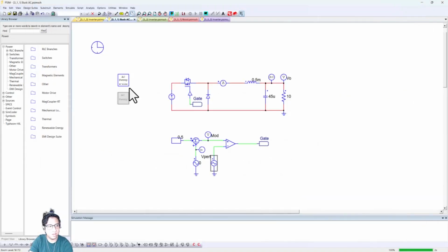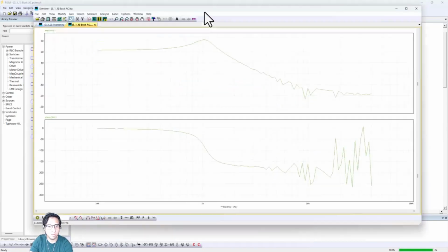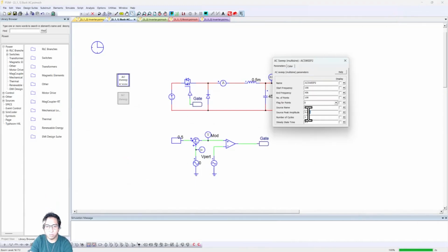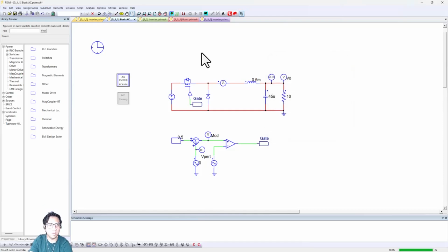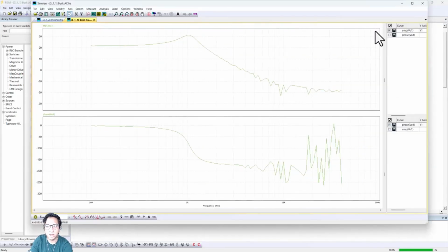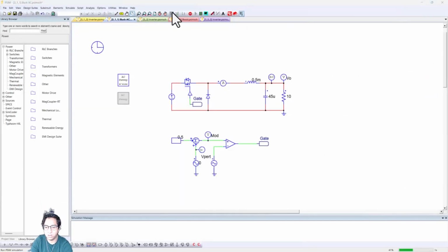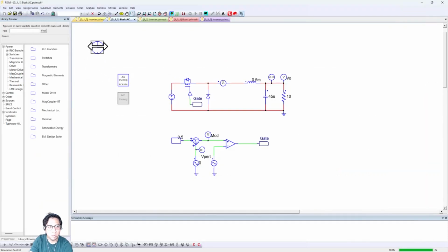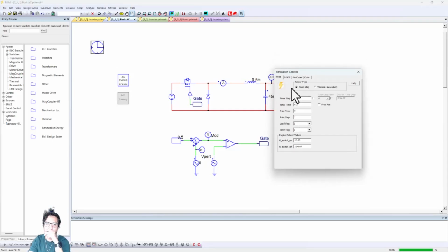The first thing we can think of is that if we look at the original plot, we are having a lot of attenuation at higher frequencies, or relatively higher frequencies. So we might try to put a bit more amplitude in there. A good trick is if you open up the sidebar here, we can save plots from this simulation and have them ready for the second one. So let's bring back amplitude. Let's bring back phase. It looks like phase is a bit better, but the main culprit here is time step. So we do need to make time step a bit lower.